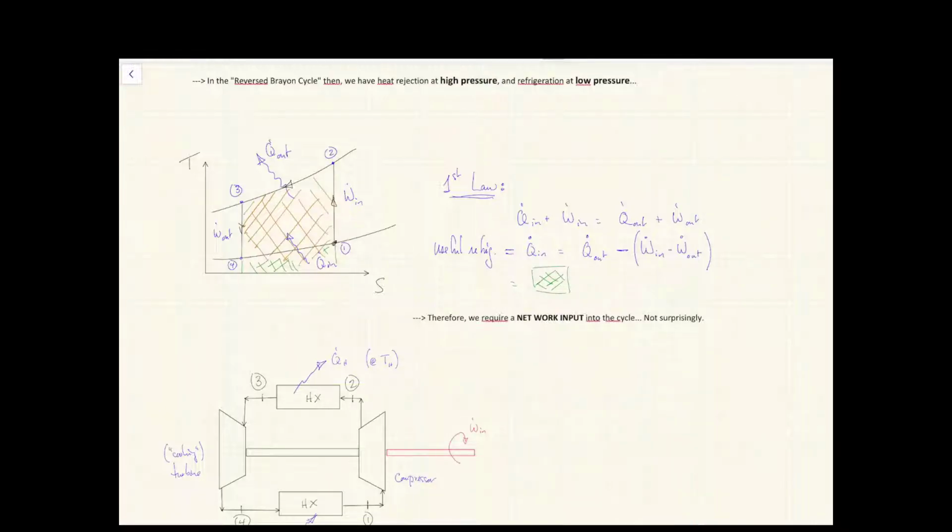So the cooling turbine is key here for doing that and getting us as low as 0.4 as possible, where we're going to dump this into the cabin. So where does the energy come from to do this, right? Given that the work out right here, which I had before, is clearly less than the work in, which I require to run this cycle in the first place. And as I mentioned, that work is going to come from the gas turbine engine.